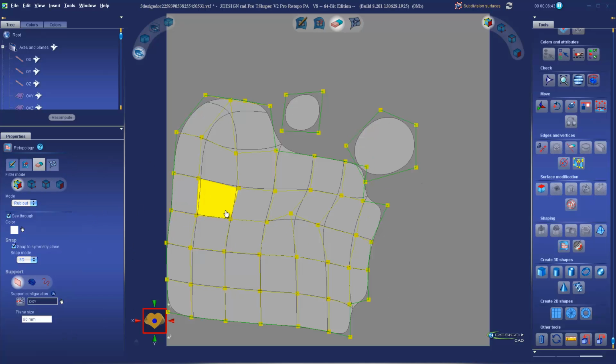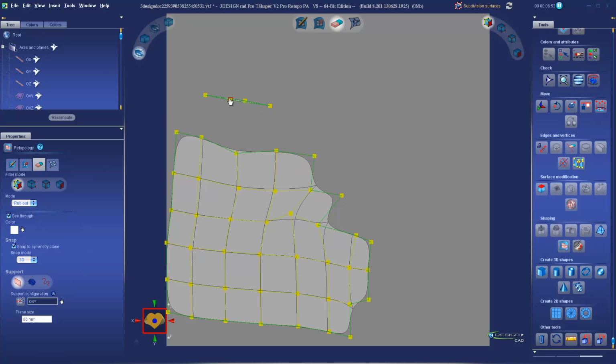The third tab is the Rub Out tab. There are some other little options here, but basically it allows us to delete parts that we want to get rid of. So if you've made some mistakes and want to clean this up, get rid of that triangle in there, you can delete points, edges, or faces. If you just delete the point, you see that collapses down to a triangle. If you want to filter and only do full polygons, you can switch to that. Or if you only want to delete an edge, you can do that. Or none would allow you to select any of the three.